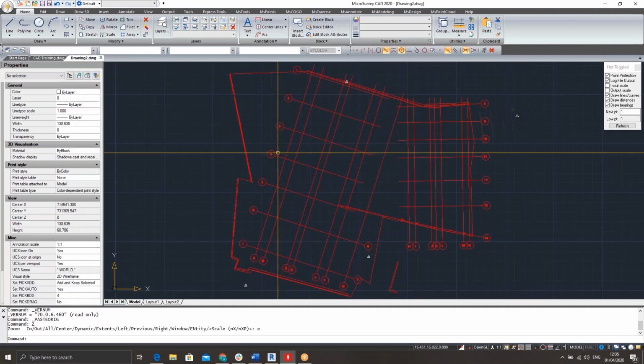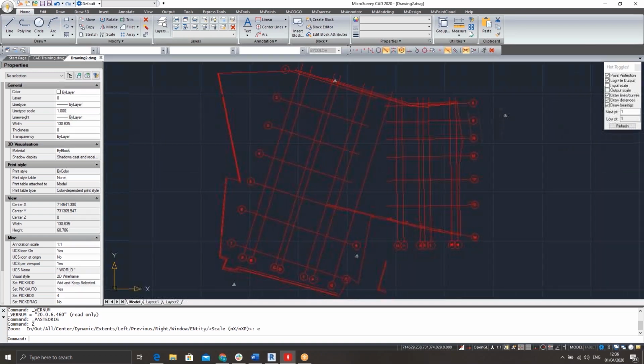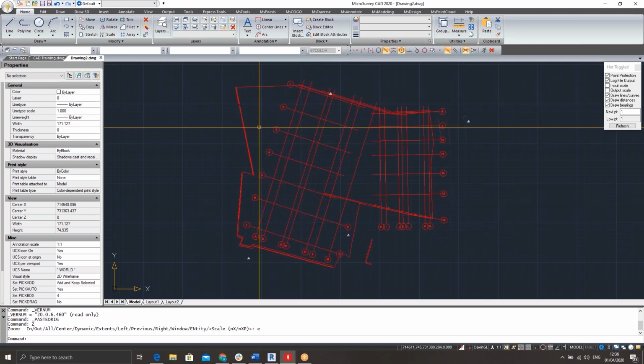And you remember the last time we did zoom extents, it brought us miles back out and we actually couldn't find our information. So now when I do zoom extents, I know what is within this drawing. And what's going to come into my model space within my field software is exactly what I can see on the screen there now. So as a habit, I just like to confirm and I like to run through a couple of steps again.